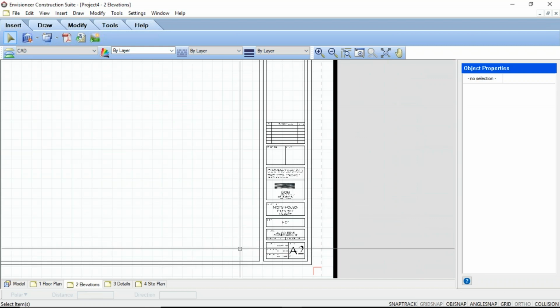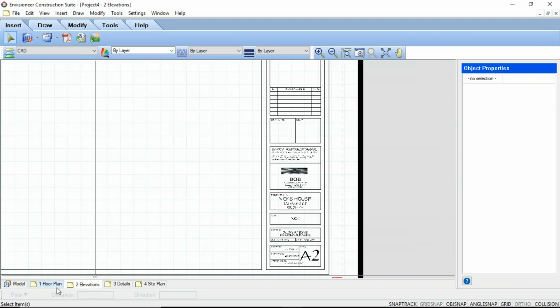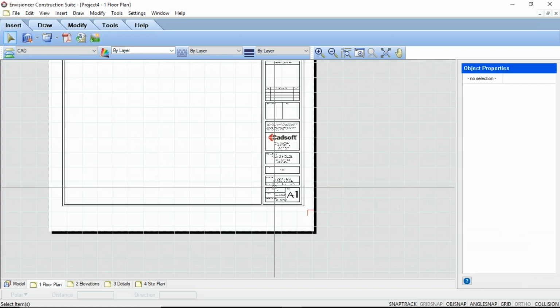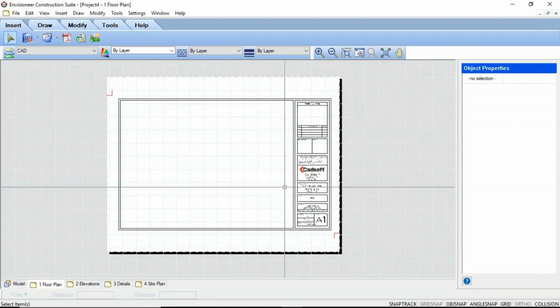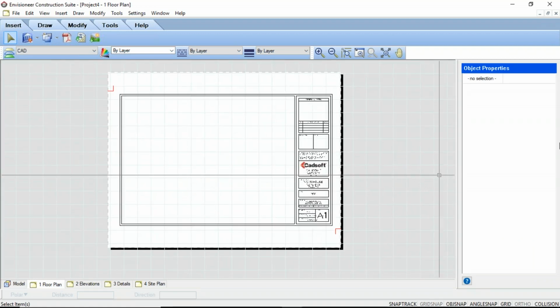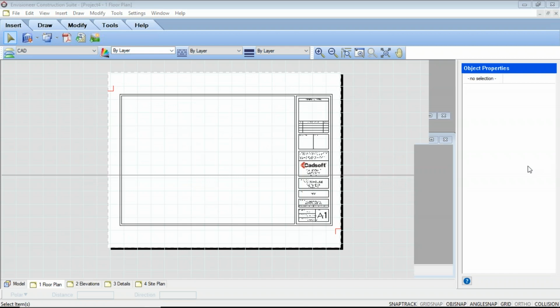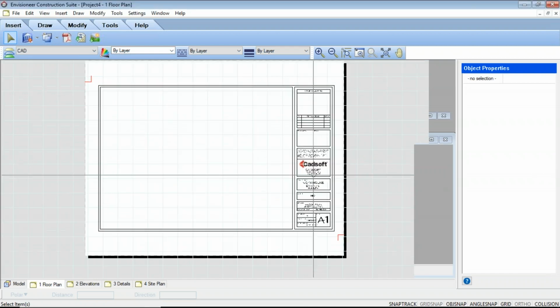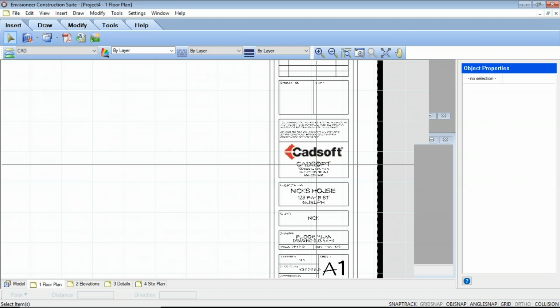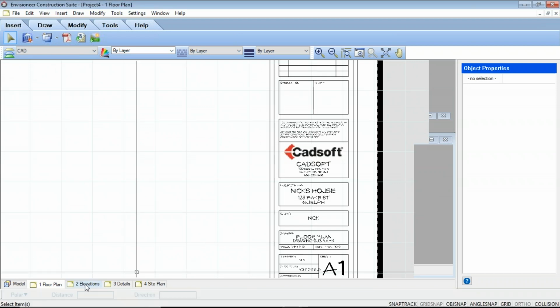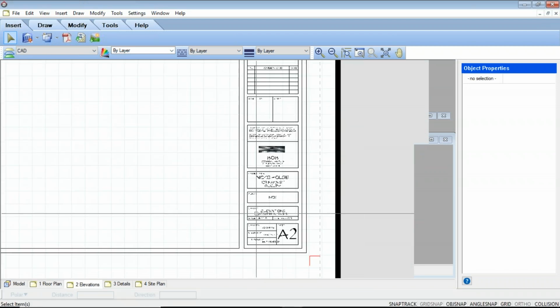So you can make those adjustments as you need to, but it's a part of the actual definition of the title block itself. So just like when we were adjusting the company information, let's just go to this title block here. This is one that we've actually adjusted.